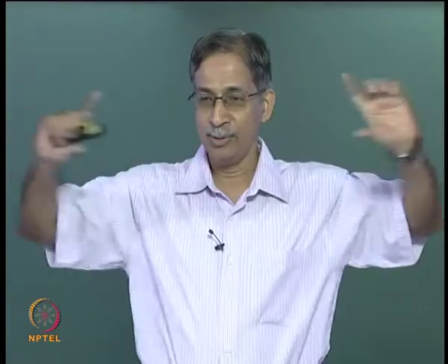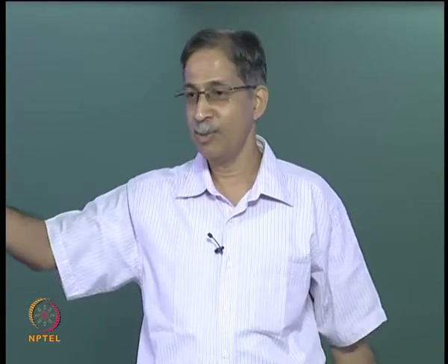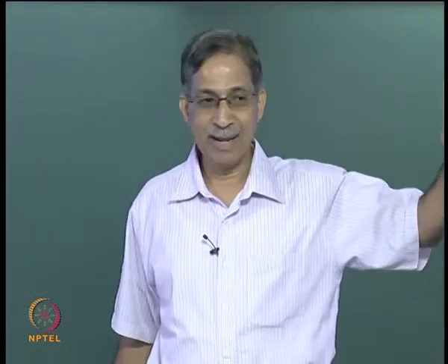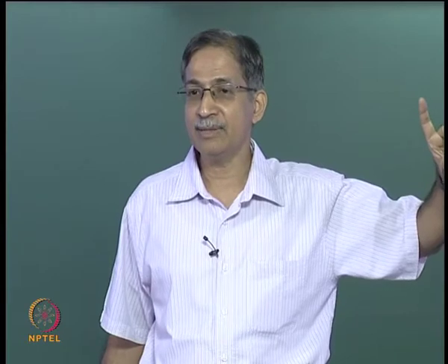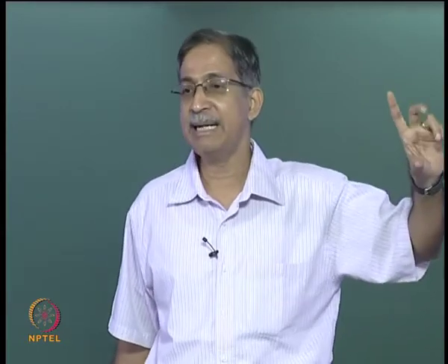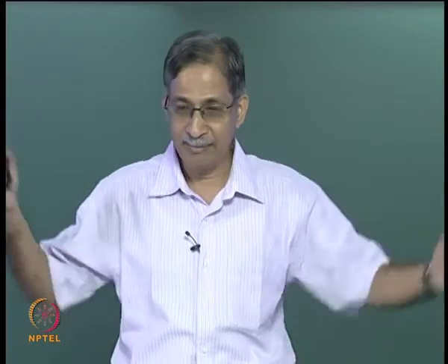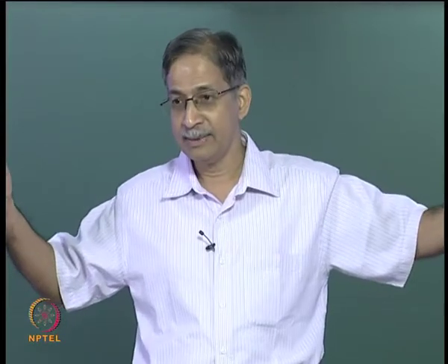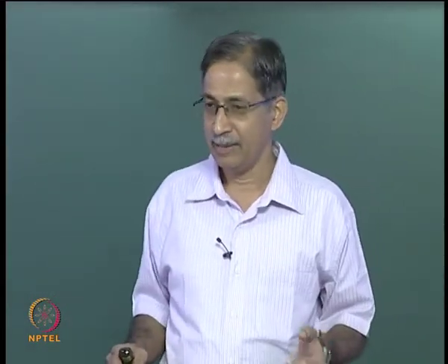So when you have a huge beam sitting on top of them, where you have the shear wall you will not get much movement, where you have the column you will get a movement, and that movement gets enhanced with time because in concrete we have a phenomenon called creep. So you have differential settlement in that beam, and if the beam is not long, 6EIΔ/L² is the kind of fixed end moment that you will get. That is a huge moment.